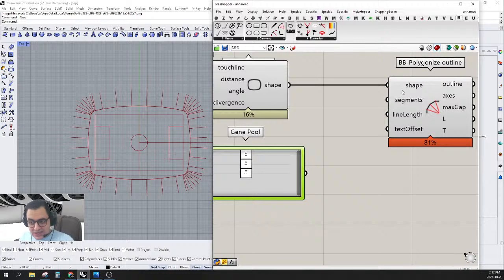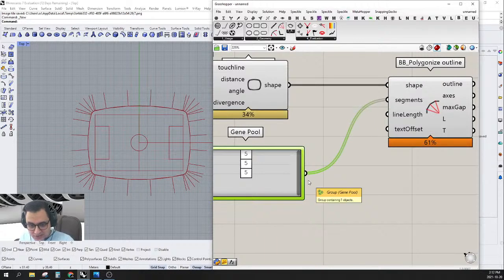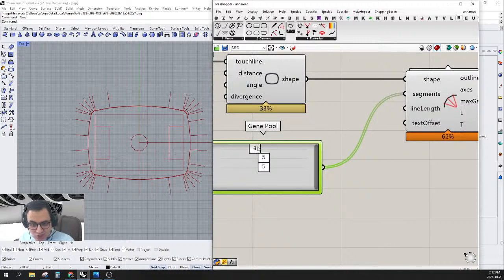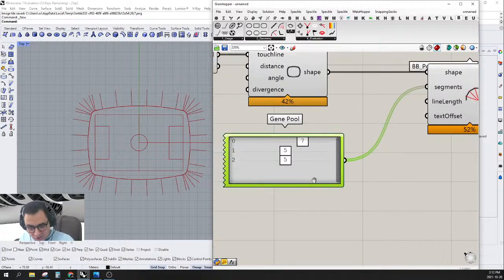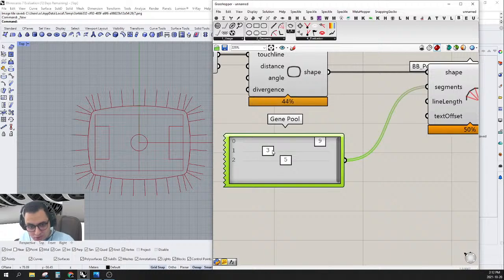And you can see that there is a segment in here, and I would like to enter this, and I can change how many segments in here in the big curve. Let's make it 9. Yeah, and in here you can see that this is the corner. So 5 looks fine, because I want more divisions, or maybe 4.